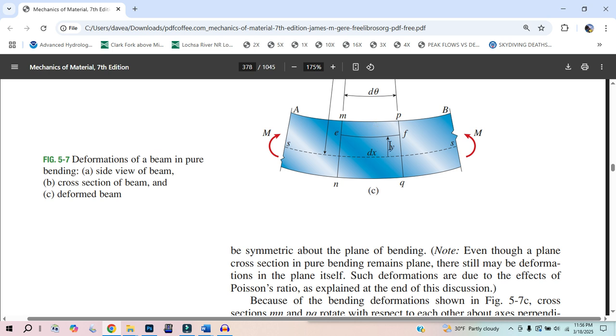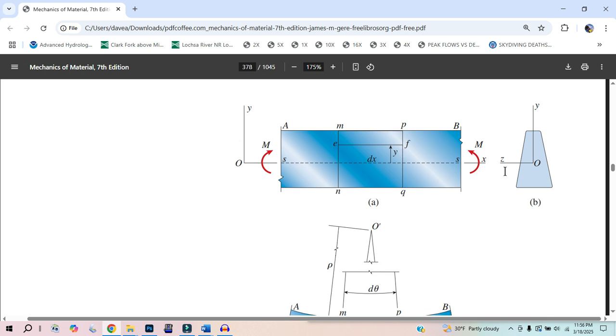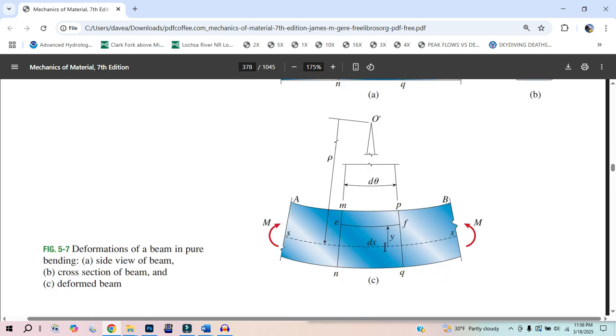And that's going to happen at this y value, from there to there and from here to here. Now this is not a square cross section, so this distance here to here is going to be less than the distance from there to there, as better represented down here. So this distance is short, this distance is long, so you're going to get two different values. Like you could get a stress down here of not much, but up here...